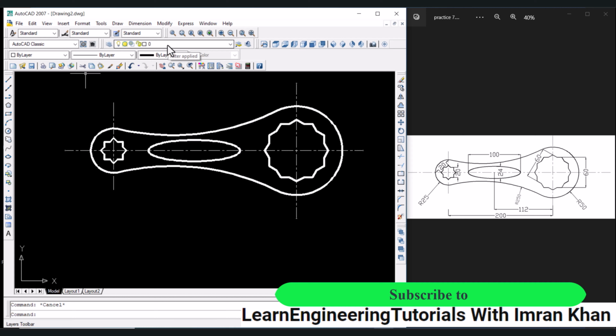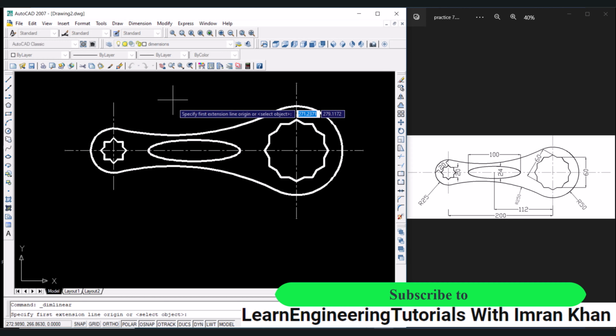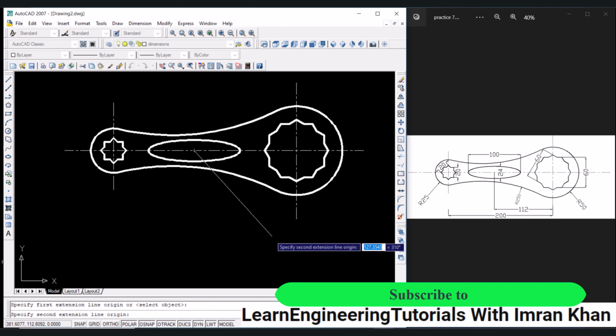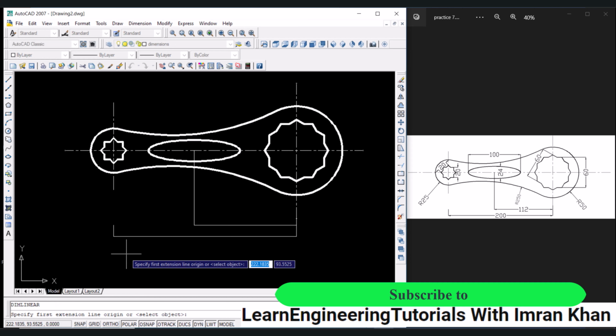For that, activate the dimensioning layer, so click on this layer option, click on dimensions. Now perform dimensioning, so click on dimension, click on linear, find out the center of the ellipse, click, bring the cursor outside, and then click on this endpoint and click, press enter again, click on this endpoint, drag this endpoint, click outside, press enter again,